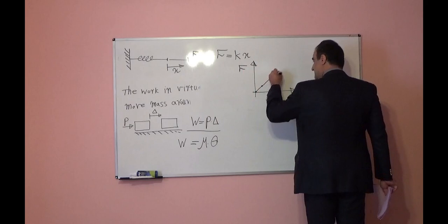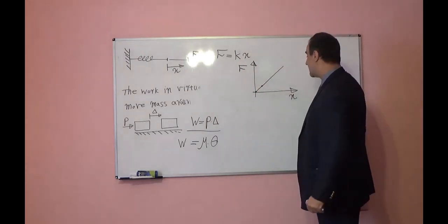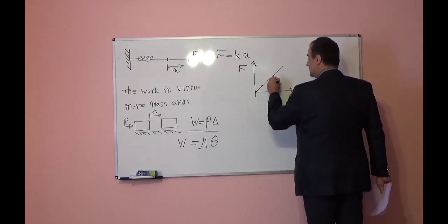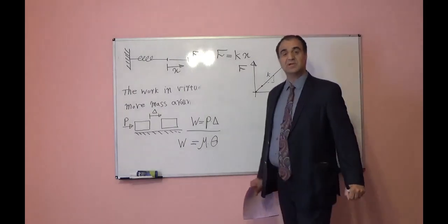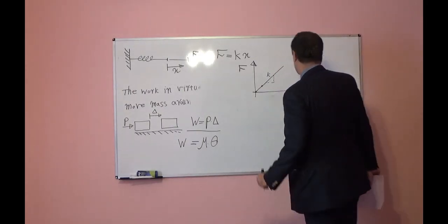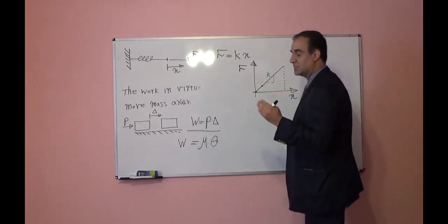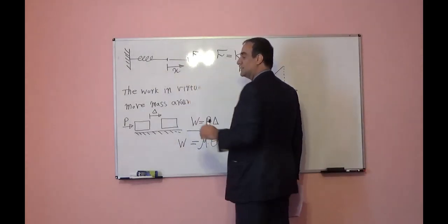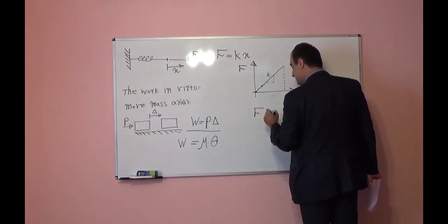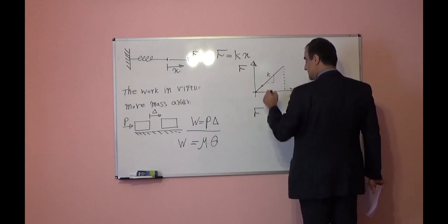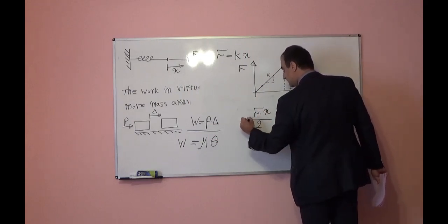If we attach these points, we will end up with one inclined straight line. And we know the slope of this line will give us the stiffness of the spring. We will show with K. Here, because we apply force gradually, our displacement increase gradually as well. Here, work is equal to force times displacement divided by 2.